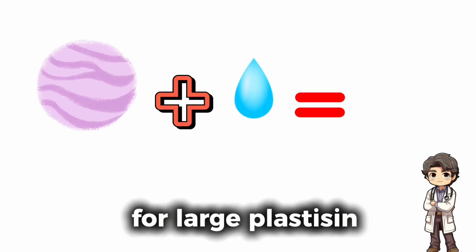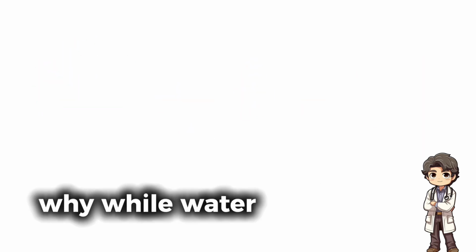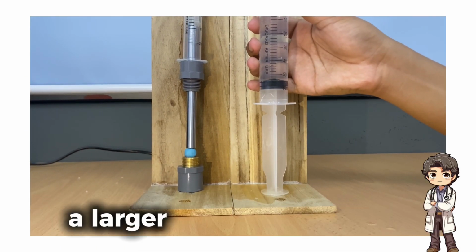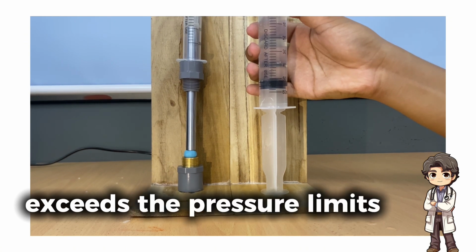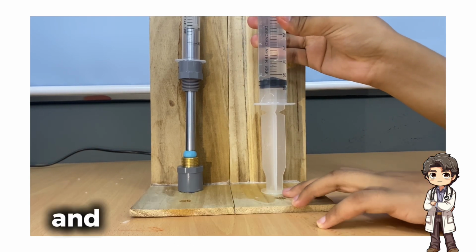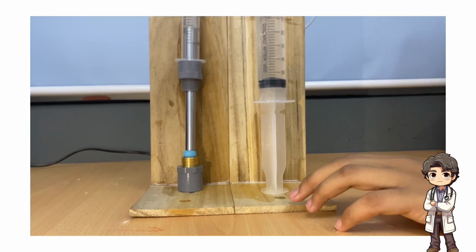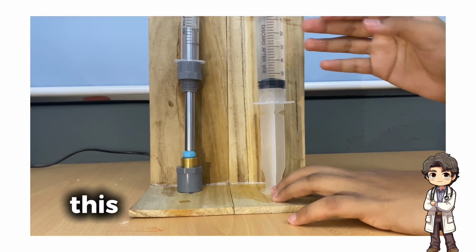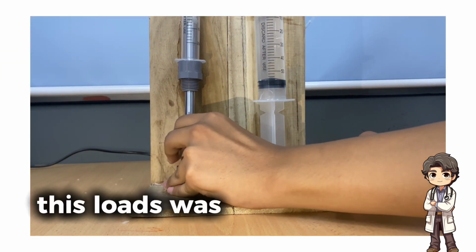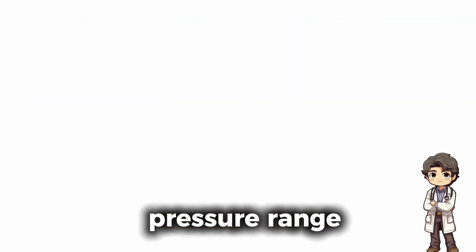Large plasticine and water shows fails to compress fully. Why? While water still transmits pressure efficiently, the force required to compress a larger volume of plasticine exceeds the pressure limits of the small syringe. The small syringe has a smaller piston area, and although pressure is high, the mechanical output force is not enough for a larger object. This reflects a limitation in mechanical advantage. The load was too resistant or large for the system pressure range.